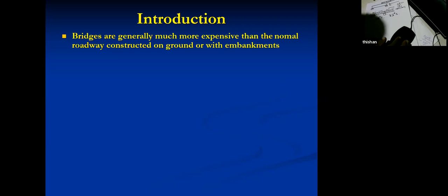But again, you have to look at the safety aspect. If it is a real floodplain, then you'll find an elevated highway is a much more preferred mode than an embankment. If you look at the Katunayaka Expressway, it's on an embankment, whereas the outer circular highway is elevated in a lot of places. In the same way, on the road beyond Matara up to Mattala, the Matara area is the Nilwala River floodplain, so in those areas the road is again constructed as an elevated highway.